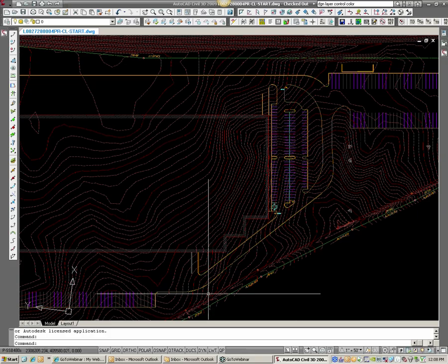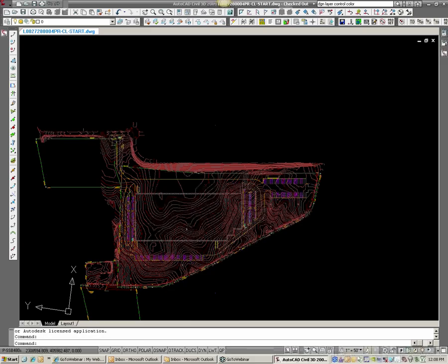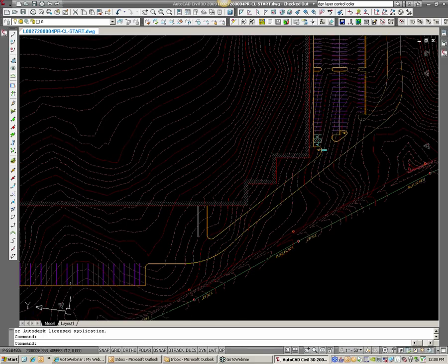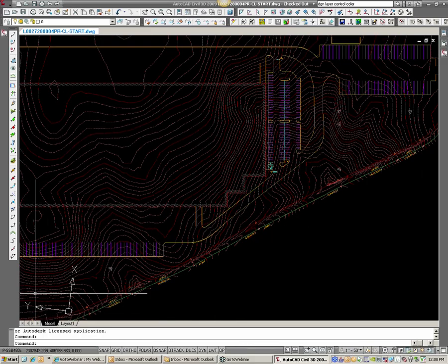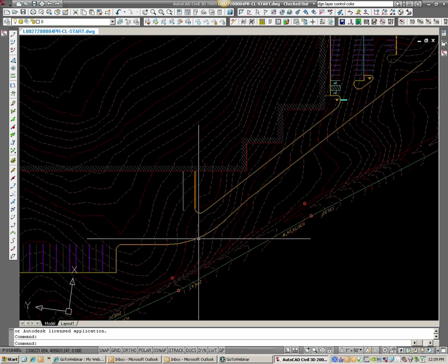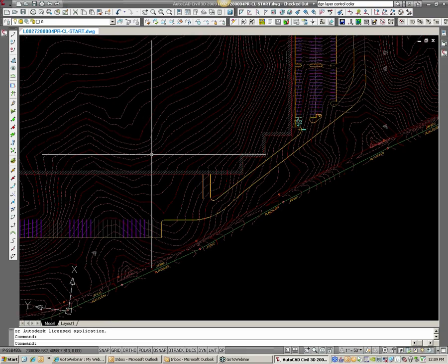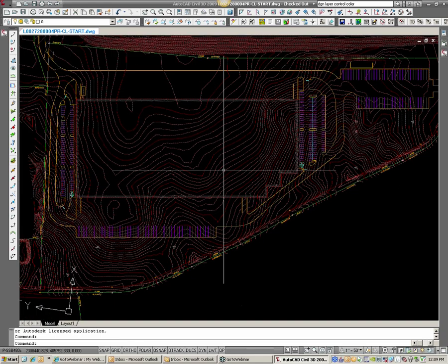Maybe I see that this is a tight spot. Just knowing this site, it all drains down from the north to the south, actually from the east to the west. You can see my drawing is rotated here. So I might do some math to come up with a 3-to-1 slope, give myself some room here, go 2%, go up 4 feet because this is a loading dock, and then guess a first floor elevation. But at the end of the day, you are guessing. On this project, I'm going to guess a correct number just because I've graded it already. And this building first floor elevation is going to be 518.40. So we're going to go ahead and start with that.